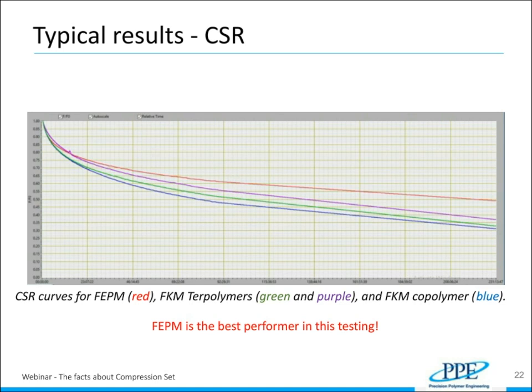And what we're essentially seeing here is the point at which those chains are no longer able to have significant amounts of movement. The system energy no longer allows them to freely move and rotate. So a higher Tg would be an indication of reduced polymer movement. So this high Tg of AFLAS-type materials could be believed to introduce more cold set effects.